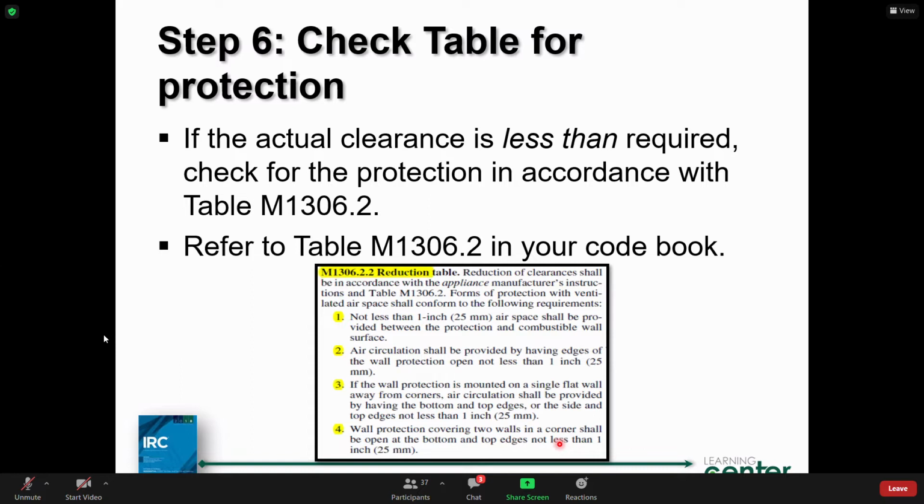If these are listed appliances, you know what a listed appliance is? That means that it's been tested in a nationally recognized testing laboratory like UL or CSA or ETL, and it's been tested for that particular function in operation as a gas furnace, a boiler. So the appliances have to be listed and they all come equipped with a label.